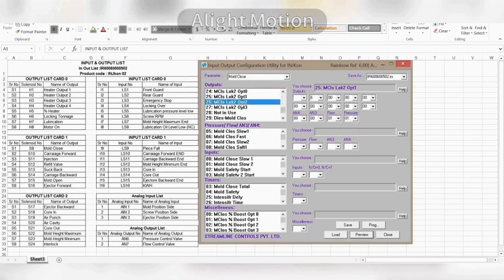Same way, mold close locking to option 2. Output number 9 and 6, and pressure 0 1, and flow 0 1 enable. Same way, mold close locking to option 3. Output number 9 and 6, and pressure 0 1, and flow 0 1 enable.